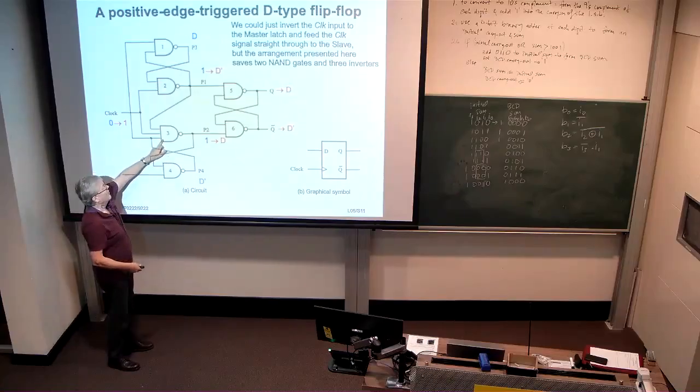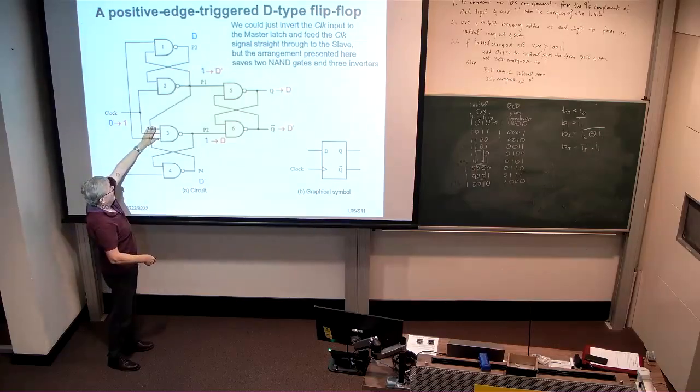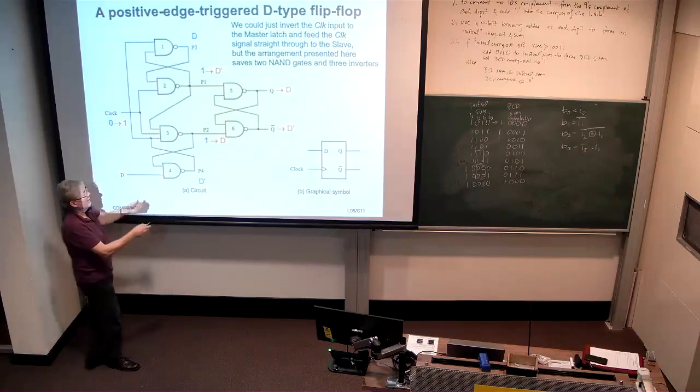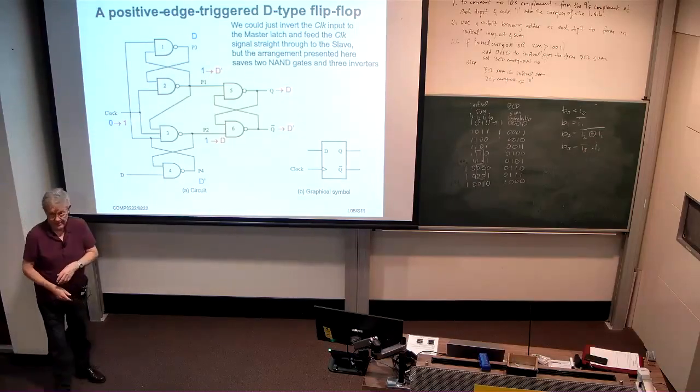So we had not D on this wire, together with now a 1 coming in, and this one is either 1 or it becomes not D because there's a D at point P3. So we either have two 1s and a not D or two not Ds and a 1. In either case, P2 is going to go to D. And by a similar argument, P1 is going to go to D bar.